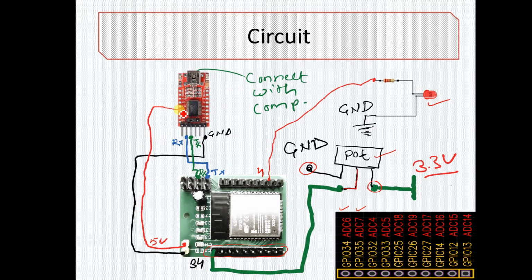After that, we have to power up the board through 5 volt and ground to ground, RX to TX, TX to RX. And finally, you have to connect it to the computer.